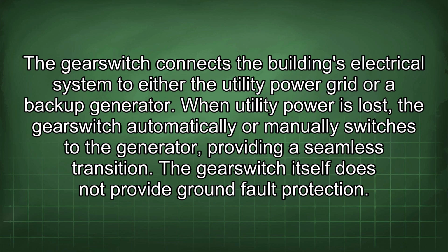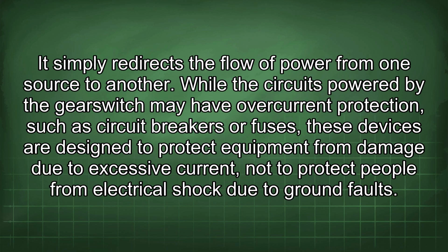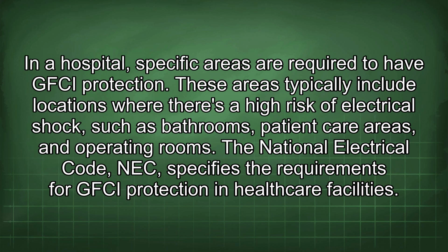The transfer switch itself does not provide ground fault protection. It simply redirects the flow of power from one source to another. While the circuits powered by the switch may have overcurrent protection, such as circuit breakers or fuses, these devices are designed to protect equipment from damage due to excessive current, not to protect people from electrical shock due to ground faults. In a hospital, specific areas are required to have GFCI protection.